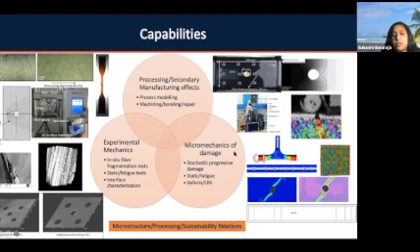Besides that, we have also looked at micromechanics of damage for polymer matrix composites, inclusive of things like residual stresses. As I was mentioning, for a particular spatial distribution of fibers, we looked at what happens to the failure envelopes, correlating the microstructure with the performance. We have also looked at classical problems such as multiple fiber fragmentation, and we have done upscaling as well. So in an actual laminate, how do not just the strains, but also the damage modes evolve.